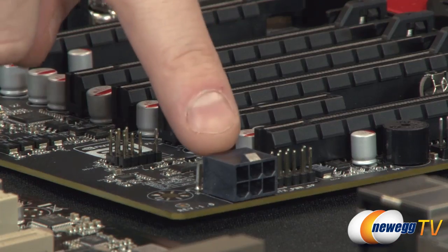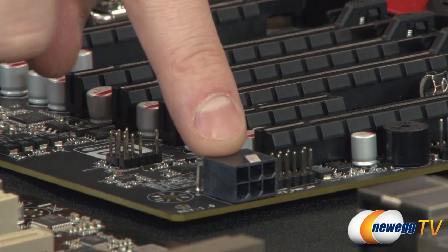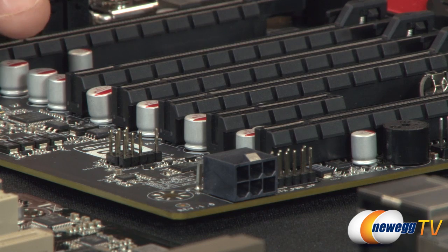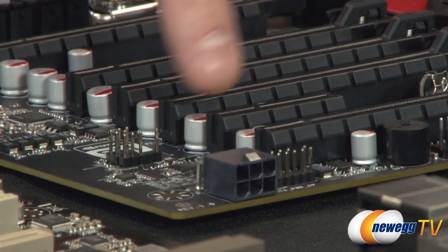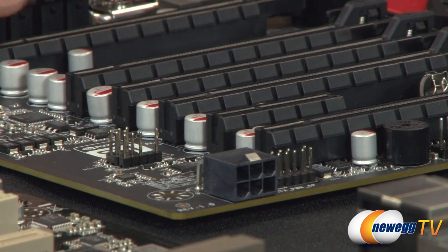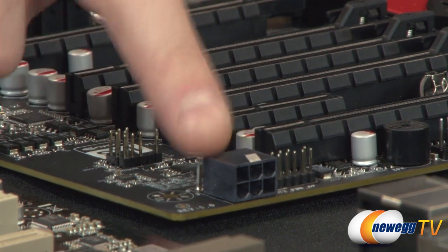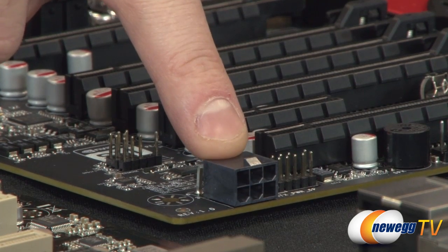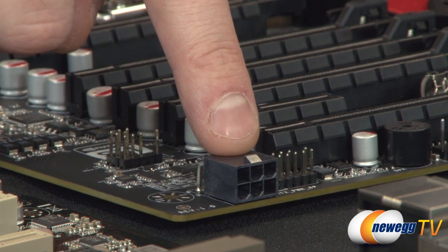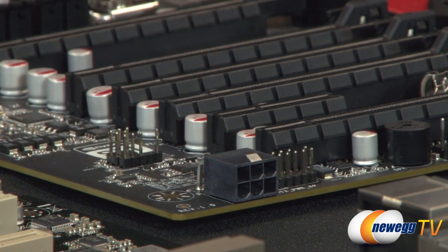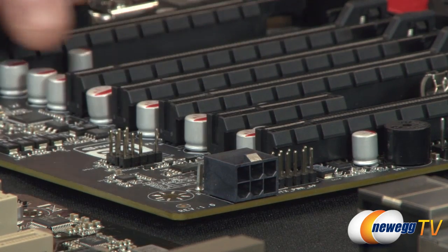There are some additional power connectors you might see from time to time. So for instance, on this X79 board here, since this board is designed to handle multi-video card configurations, sometimes the power that's available directly through this little slot, or particularly if you're actually populating a lot of these, separating the power out over all of those can lead to some voltage droop or the power to drop out at some time. So they've added this extra 6-pin power connector to the board. This is a power connector that you would typically see on a graphics card. It's a PEG or PCI Express graphics connector. But basically this is there to plug in if you're really maxing out the board.